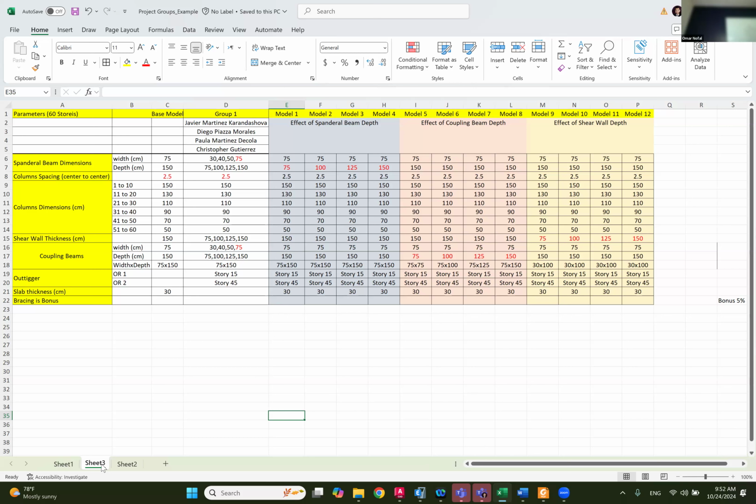And one other thing, I want to see the impact of the column spacing. Since all of you only used one column spacing, like you used 2.5, you used 3.5, you need to provide your data to the other team so that he can plot the impact of the spacing. Okay, so that's one thing that I want to see. Hopefully you guys have the models right, and can share the data between each other so that you can plot the 3 curves, or how many curves, I don't know, like 3 curves, and see the impact of the spacing between columns on the total drift, interstory drift, shear lag, whatever parameters that we are studying.